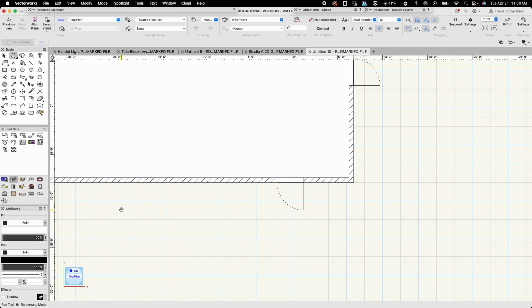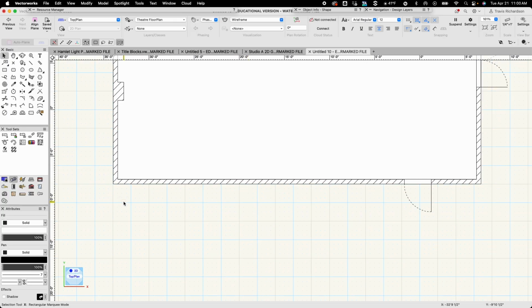There's another door in the bottom wall of Studio A over here on the left-hand side. And from this one, it is 3 feet, 4.5 inches in. So I'm going to select my double line tool. And since I'm coming from the left, I'm going to switch to left control line mode and start on this inside lower left corner. I'll click to start that and tab in to tell it 3 feet, 4.5 inches. And I'll click to complete that.